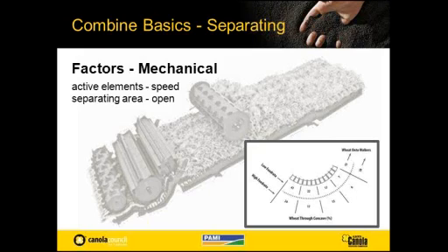And that's because the relative speed of the material moving through the concave is quite low. So it can now fall down or get forced down through the concave. But as it travels farther back on the concave, it's picking up speed and it wants to travel along the top of the bars along with the straw and everything else, and you can see that decreasing rate.